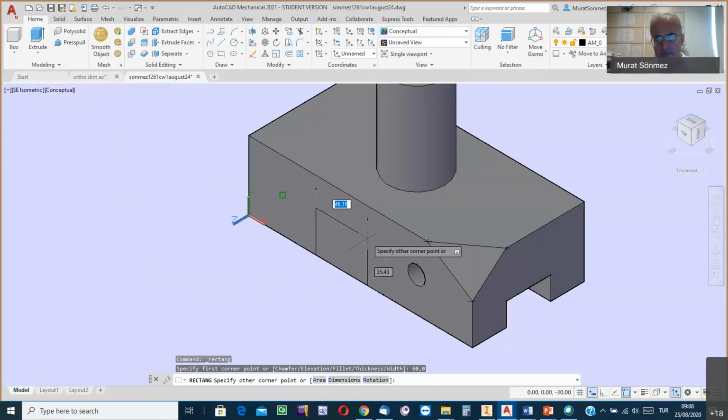And now, since the dynamic input button along the status bar is on, after starting a process you can always find a useful simulation. Here in the simulation, I think it is understandable. The highlighted box is ready to accept the width value. And after clicking the Tab key, the other box will be active to gather the height value.